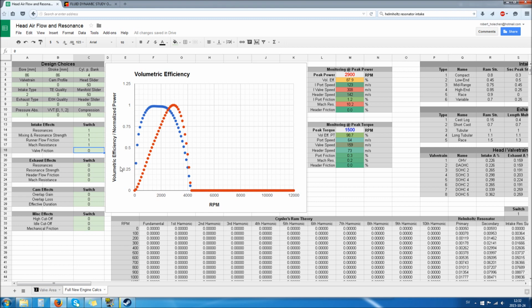And then we have the little effect of the valve area. When your cam is pressing down on the valve, that opens up a cylindrical surface which the air can rush through into the cylinder. And in order to get through there, you encounter a bit of flow resistance depending on how much you open your valves, and that is determined by the cam profile to a large extent.